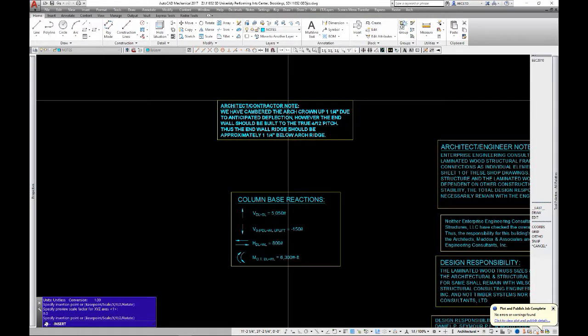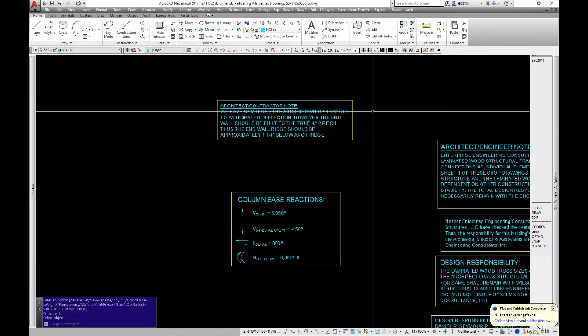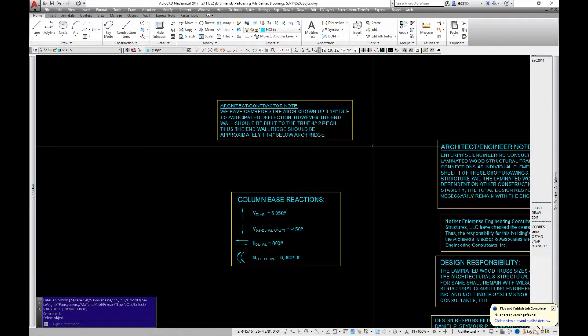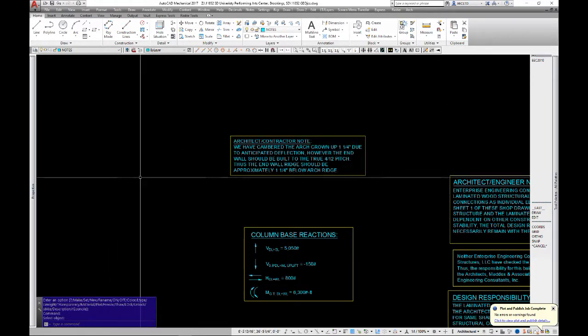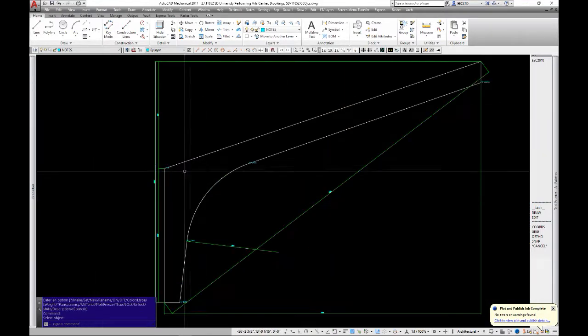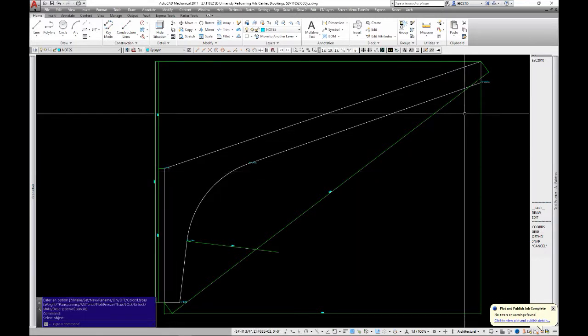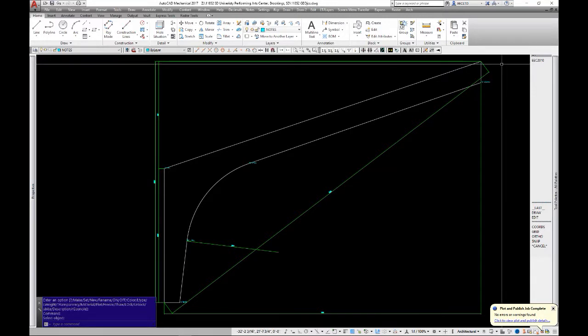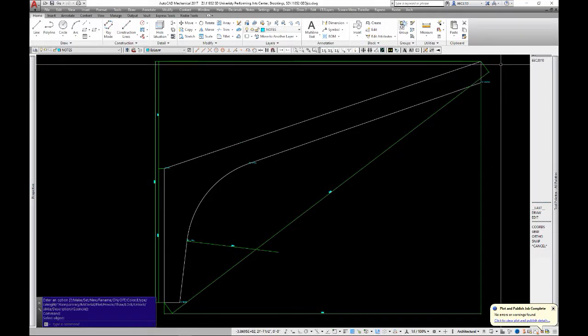Here's an end wall camber note. There are times when we have an arch, where do we have this arch? So this arch, if we anticipate that there's going to be a large amount of deflection from dead load, there's many times that we'll camber this up, say 1 inch, 1.25 inches.